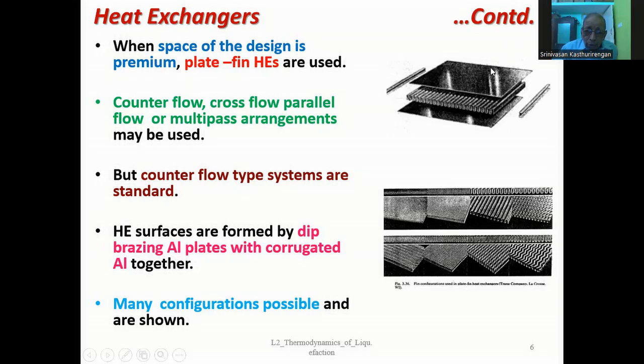One gas can flow through the corrugation on the upper side, as well as another gas, the return gas or opposite gas, can pass through the lower corrugations. Because of this flow, the gases can interact very well in between the heat exchanger plates, one on one side, one on the other side. Due to that, there is very good heat transfer taking place between the two sides.